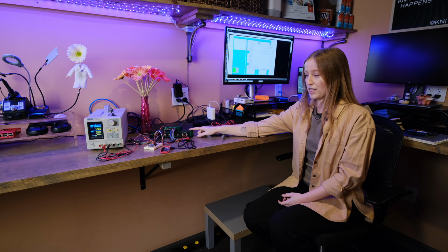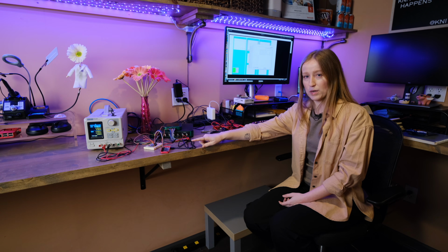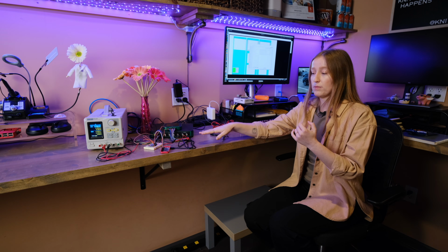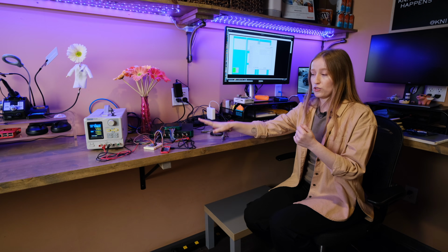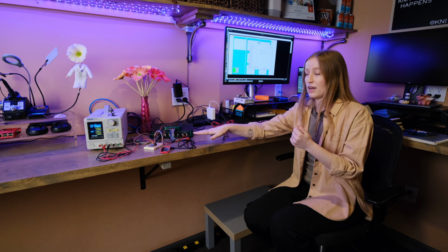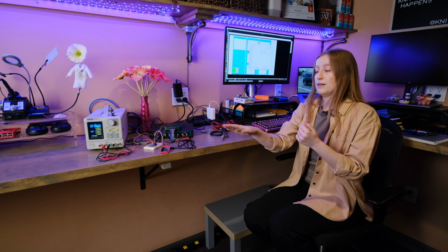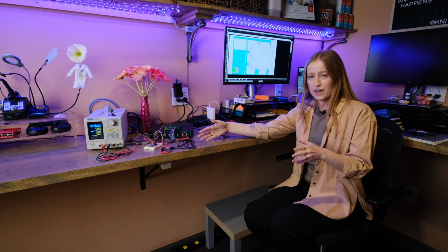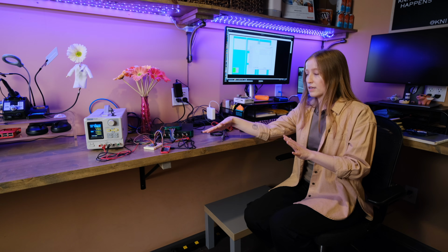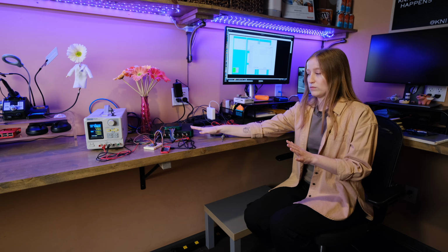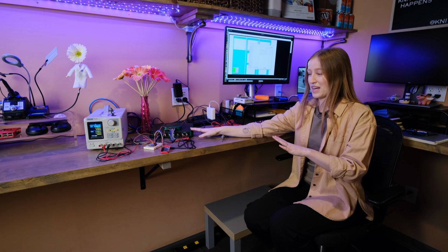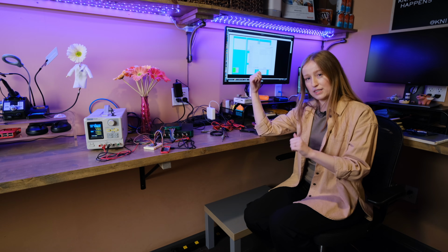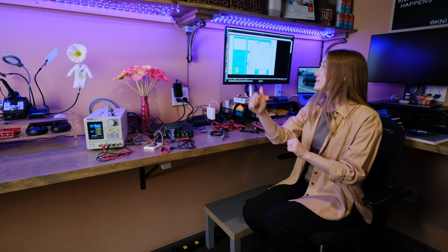So yeah, this logic analyzer is validating what the Raspberry Pi is outputting. So that does two things. I can prove in the script that I'm writing to drive the digital input of the AD9850, which did take a little bit of trial and error because it has an SPI interface that's a little bit unique. So the logic analyzer was very key in figuring out how to get my script to match what the AD9850 datasheet called out for its digital interface.